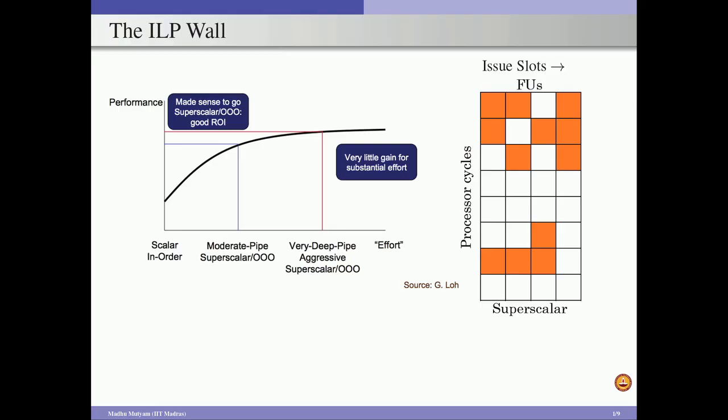So, in summary, applications may not have significant instruction level parallelism to utilize with our aggressive, very deep superscalar processor. Also, the superscalar processor design cannot tolerate these high latency events, because once the application does not have enough instruction level parallelism, we cannot hide the latency incurred by load requests which miss in the L2 cache or L3 cache and so on.